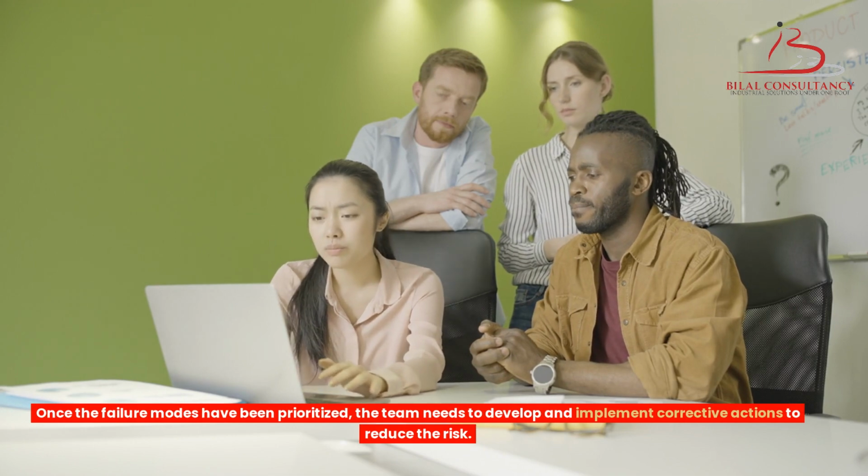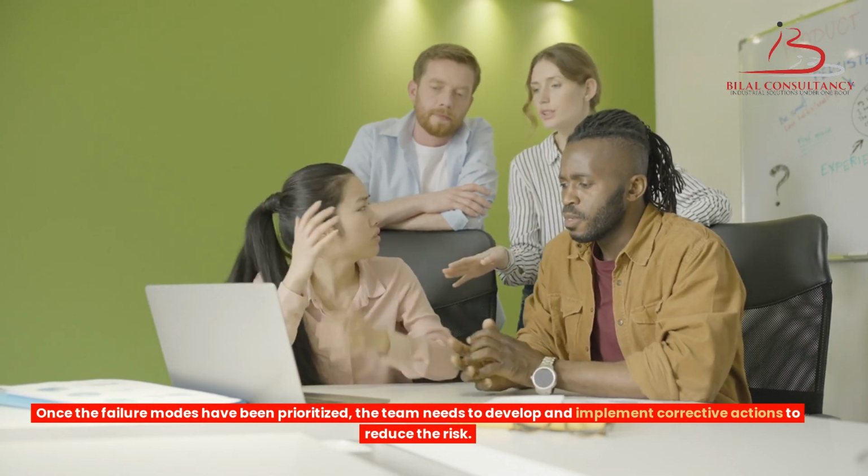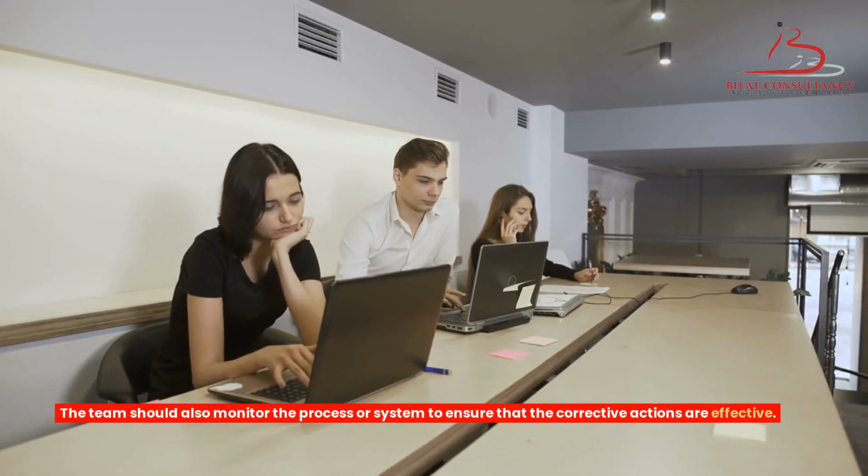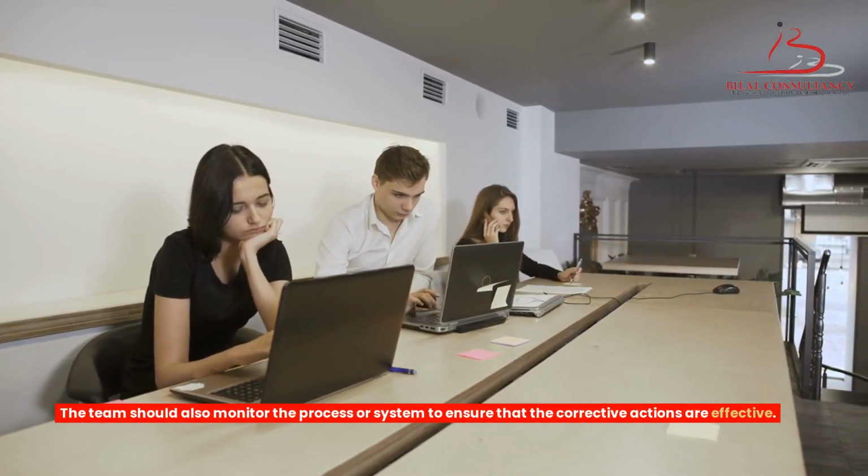Implement and monitor. Once the failure modes have been prioritized, the team needs to develop and implement corrective actions to reduce the risk. The team should also monitor the process or system to ensure that the corrective actions are effective.